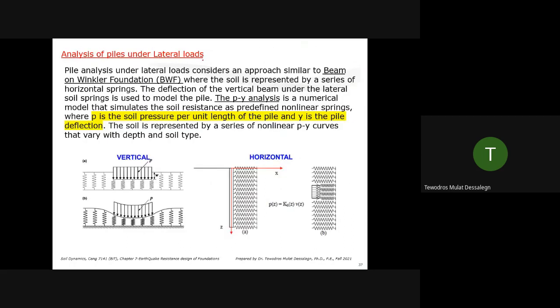So, analysis of piles under lateral loads. If you have a lateral load, significant lateral loads, which is expected during an earthquake, then the way we analyze it is similar to a beam on Winkler foundation. You have seen a foundation beam on soil. The soil can be represented by springs, right? Pretty straightforward. And that approach usually is called the beam on Winkler foundation.